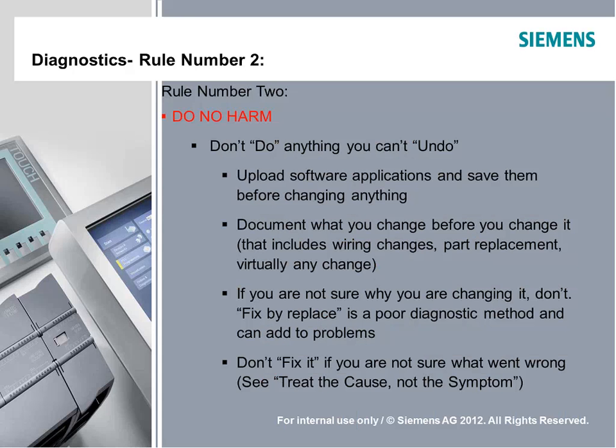If you're working on a PLC and you think you need to change something or revert back to a prior program level, upload the software first and save it. Then go and do any changes you want to do. Just make sure you have a path back to where you were. If something you think might have been the problem does not solve it, let's not leave that last fix in there.